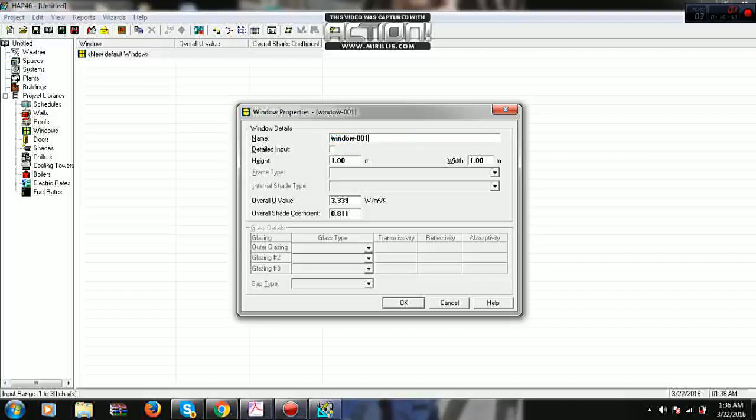001, and as I told you, if you know directly the U value, you can give the U value here. So what is the U value as per local Qatar standard? The overall U value for glass in Qatar is 2.1. Its average value is 2.1 with shading factor 0.8. So just note down these U values in your notebook, so it is going to be easy to remember.